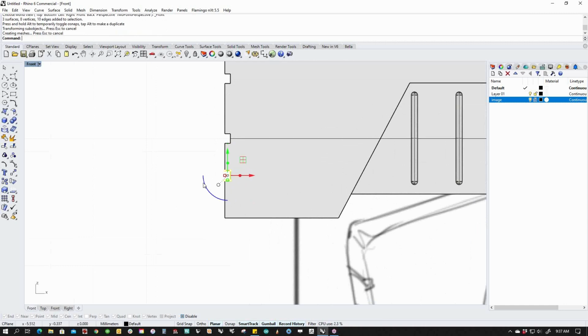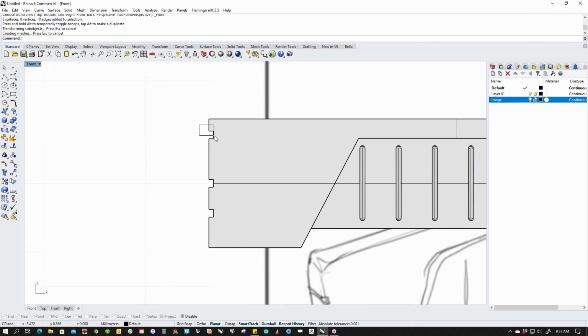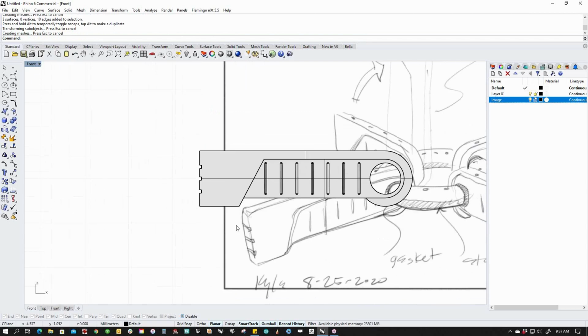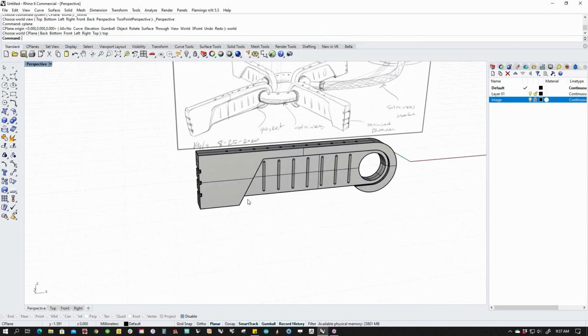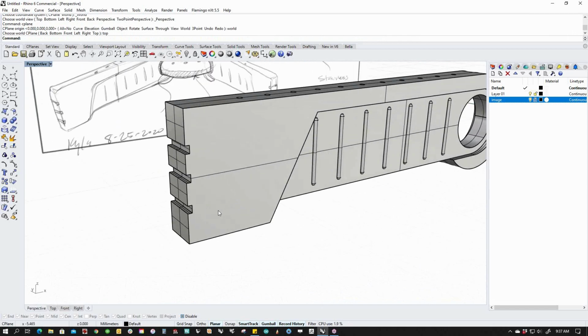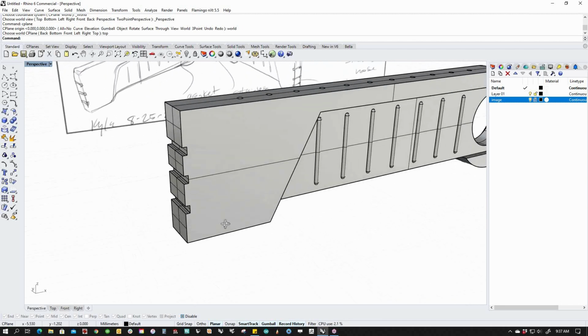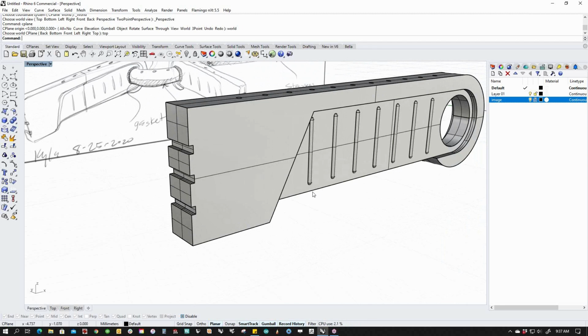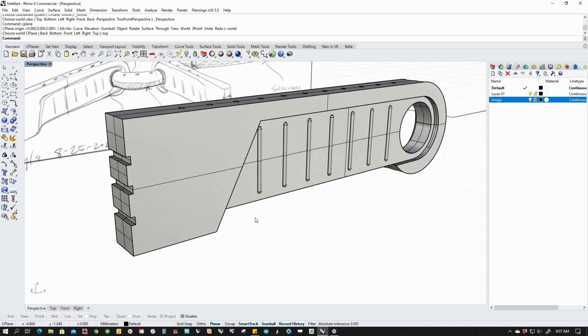Ta-da. Look at that. I can just move this thing. And I can say that looks more like my sketch. Magic powers. Cool, huh? Now, that would not have worked if this was a compound surface. The only reason this works is because it's just flat planar surfaces, right? The second I start adding a curve to that and I do it, the whole thing goes wonky. All right, so that's one of the cool things about working in basic shapes and building up from there.